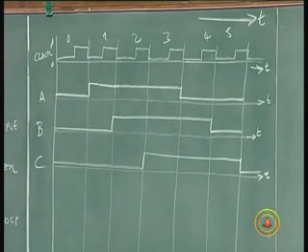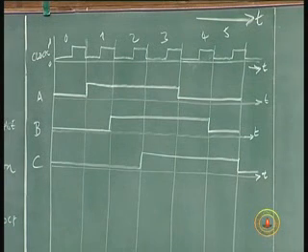That's all. 1, 0, 0, 0, 1, 0, then 0, 0, 1, 1, 0, 0. So it will only repeat, a shift register. That's called a ring counter. A counter wherein we use the output of the last flip-flop back to the input of the first flip-flop. It's called a ring counter or a recirculating shift register, they call it. You circulate again and again the same pattern.